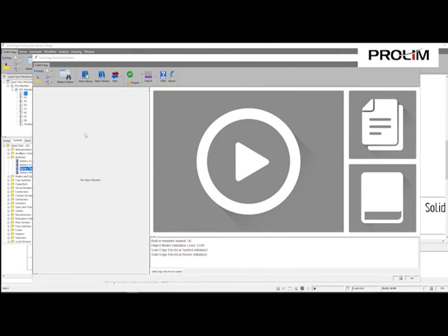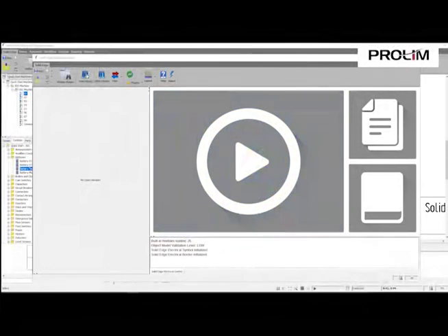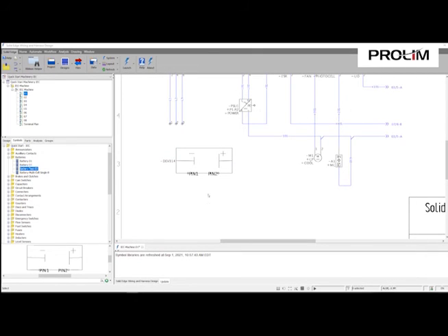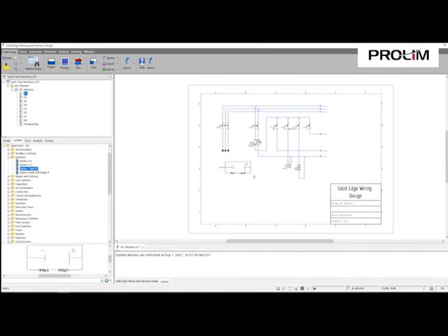So that's the basics of the Solid Edge Electrical Symbols user interface and environment and methodology. Let's go ahead and close the symbols for now. And now we're back into our design here. Now let's go back to our launch tool, and we're going to go into the electrical parts. So again, this is going to be another environment that we're getting access to via the harness design software.